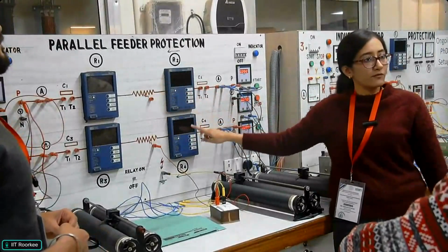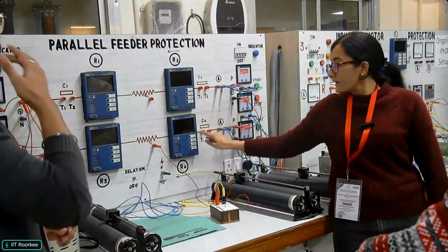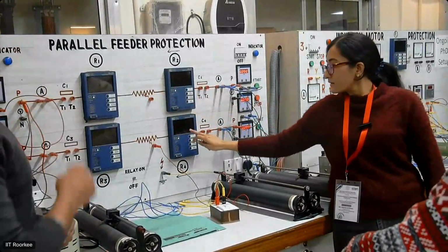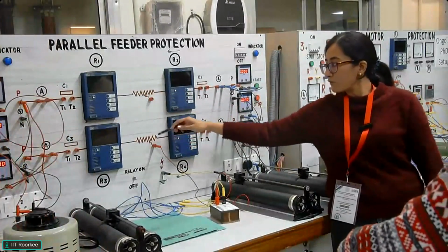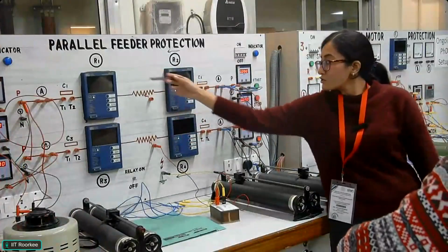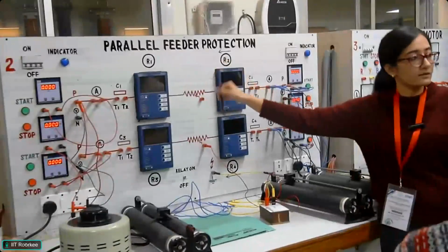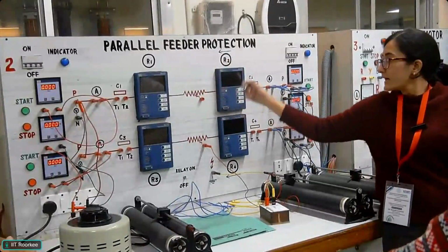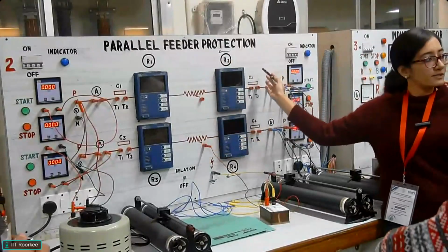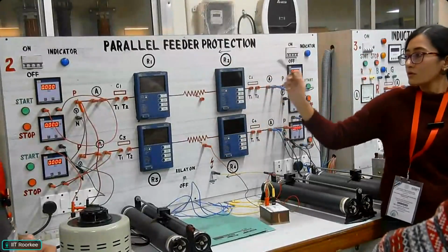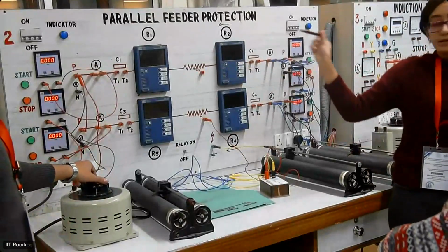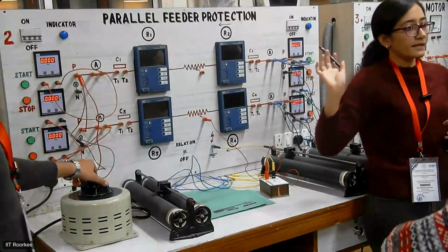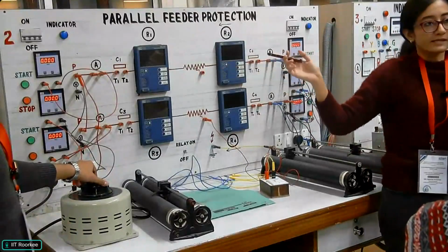And what if in case of a failure scenario, maybe failure of the circuit breaker? We design it in such a way that if R2 fails to operate for a fault in the circuit, R1 should operate at its value and provide protection immediately, and similarly for R1. Or a radial feeder or ring main configuration. There can be different possibilities. Clear?